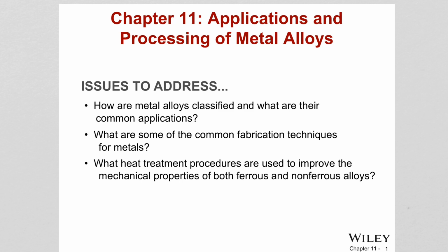So, when we are selecting materials, the most important thing is we look at the properties, and the properties will change based on what type of processing technique you are using, and it will also depend on the composition of the alloy, and on whether you have applied a heat treatment, because the heat treatment will change the microstructure, therefore the properties.